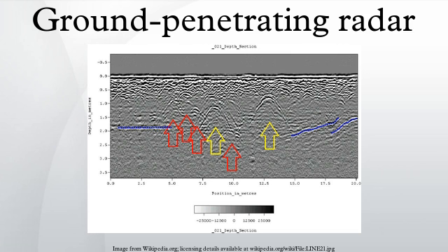The principal disadvantage of GPR is that it is severely limited by less than ideal environmental conditions. Fine-grained sediments are often problematic because their high electrical conductivity causes loss of signal strength. Rocky or heterogeneous sediments scatter the GPR signal, weakening the useful signal while increasing extraneous noise.